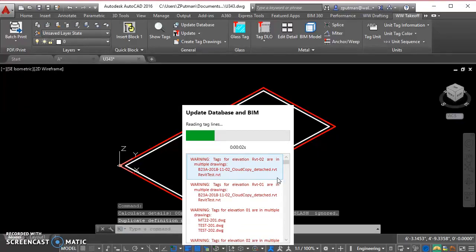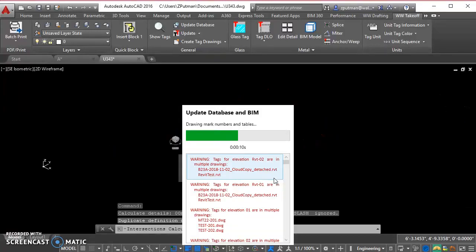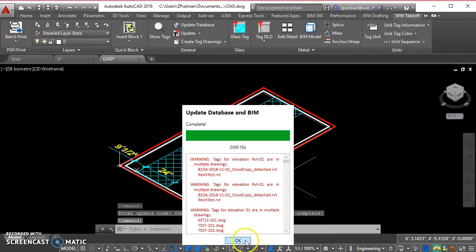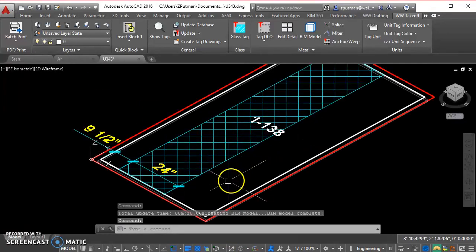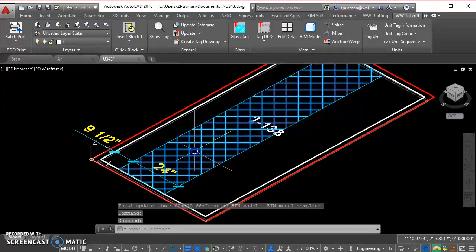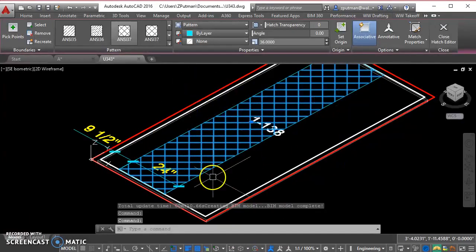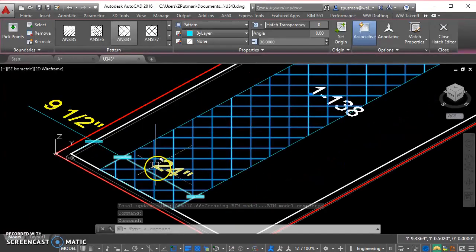So if you're doing this in AutoCAD without Revit, you would have to put your information on the glass tags manually, and then make your little pattern drawings, and you'll see this feature come up. So this is using hatch pattern B, which isn't the slash lines, it's crosshatch, and similar placement.